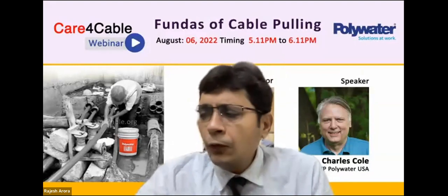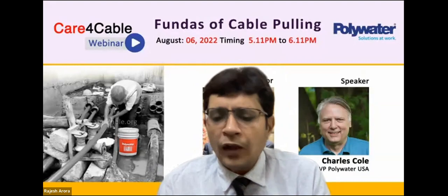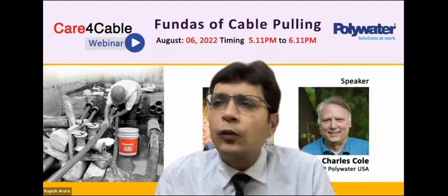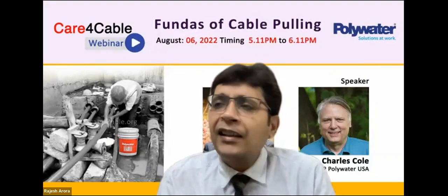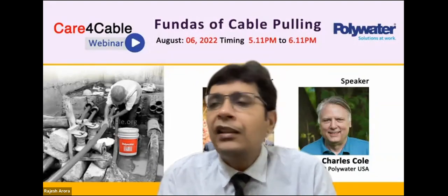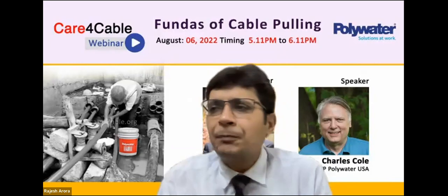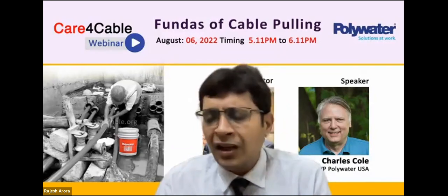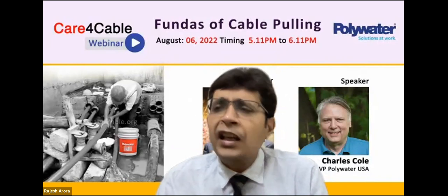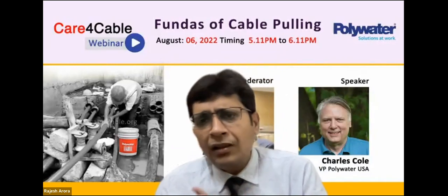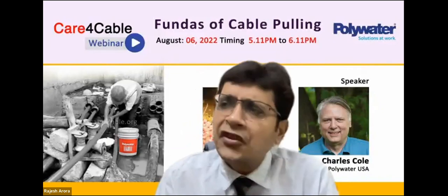Now, I would like to give a brief introduction about how the cables are laid in the Indian scenario. There are four methods. The cables can be laid directly in the ground by direct digging. They can be drawn in ducts, pipe, or HDD pipe, or it may be trenchless technology. It may be laid in racks in the air. Racks inside a cable tunnel is another option in the substations.